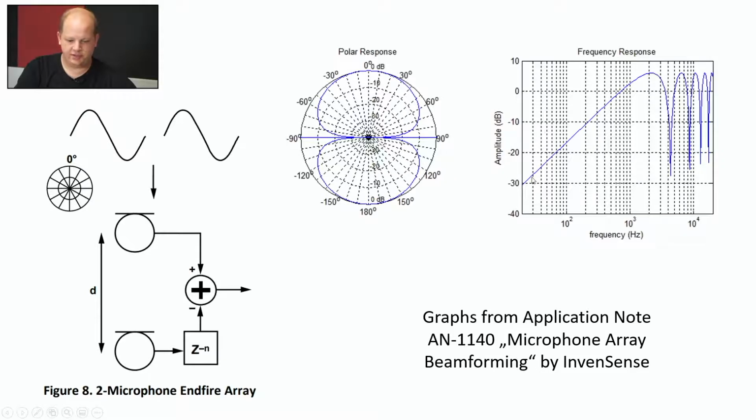What you can see here is that the frequency response of this figure-of-8 will be quite odd, let's say. We can compensate this in our plugin. What's important to know is that there is a band limitation. So the z-axis in our plugin will work up to, let's say, around 2 kilohertz. But there are many cues in this frequency band, like voices, different sounds, percussive sounds sometimes. And this makes it very useful to have really this vertical plane.